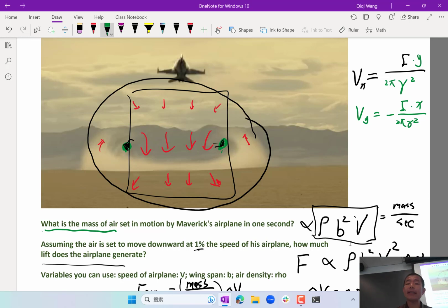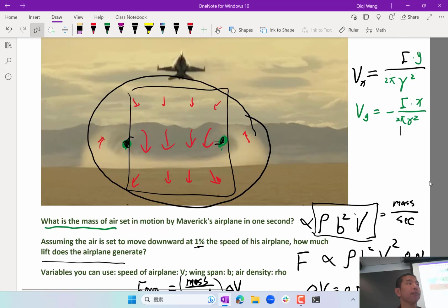So that's something we'll look at more analytically next week. In particular, we'll look at induced drag, and how induced drag depends not just on the distance between the two vortices, but also on the distribution of vorticity along the span. That's going to be a more calculus and analytical approach.